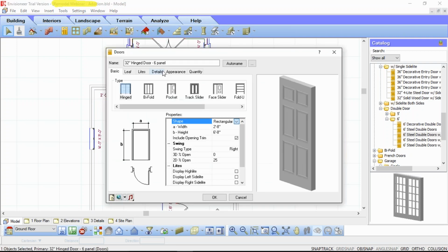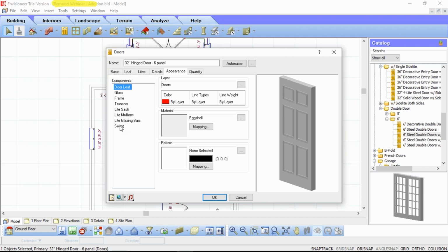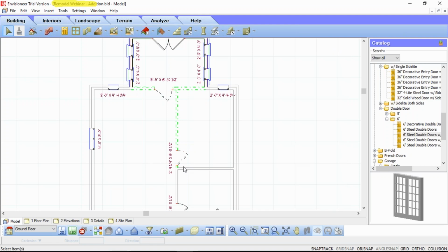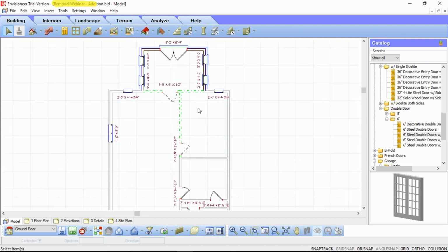Lastly, I'll just quickly do this door again as well. Choose all of the items here and just quickly change the line type to be dash dot. Click OK, and there now we can see what exactly is going to be demolished, what's existing, and what is new.